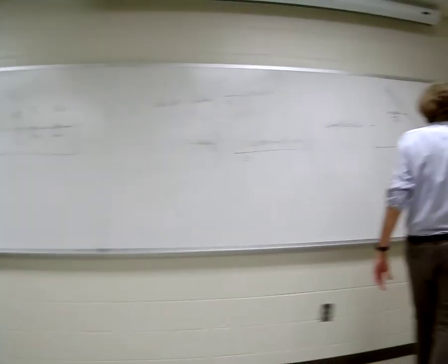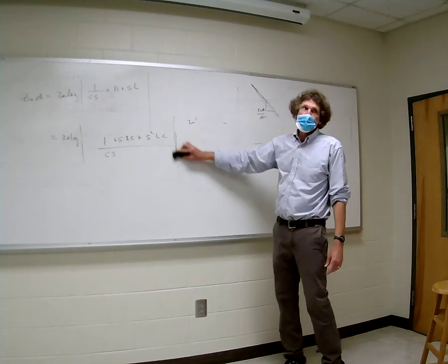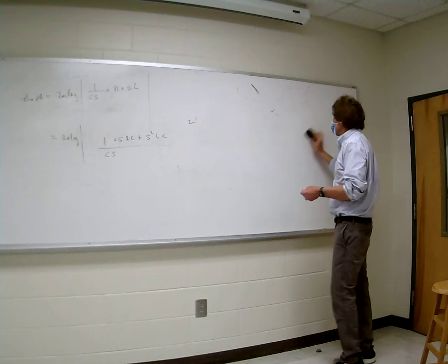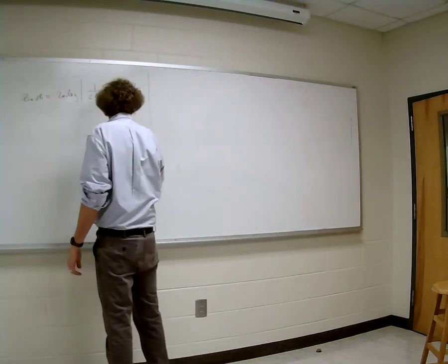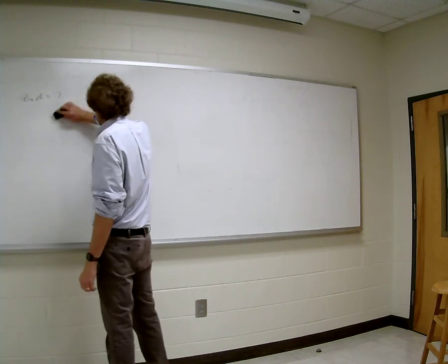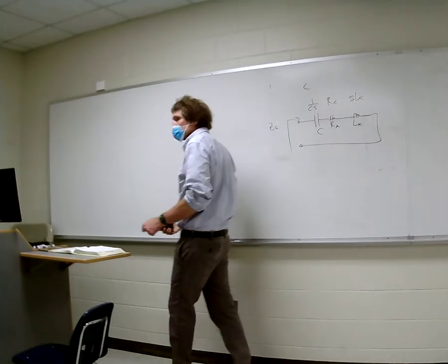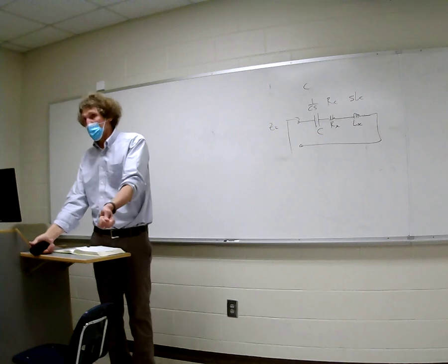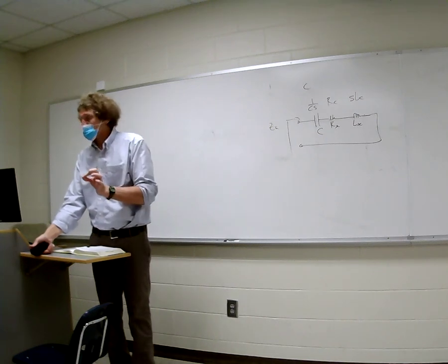Anybody? What is it? It's what we're going to always measure things with respect to. That's the definition of a ground that electrical and computer engineering people use. And it's usually a voltage, right? It's almost always a voltage. So when we have something at ground, we know any other voltage measurement in that circuit is with respect to ground. We usually take a lead and clamp it to the ground, and then we just have one probe and we measure the other voltages. That's normal.